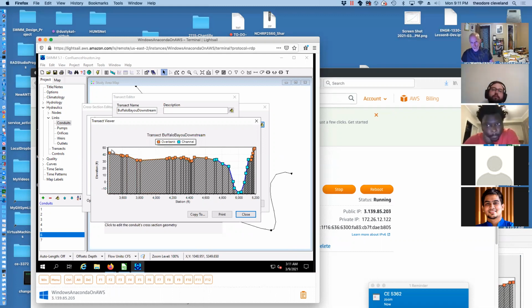So should the water get, in this case, deeper than 42 feet, in reality, it would be expected to spread to the left of the diagram. In our computer program, we've artificially restricted the ability for it to spread, which we as modelers would have to be aware of.